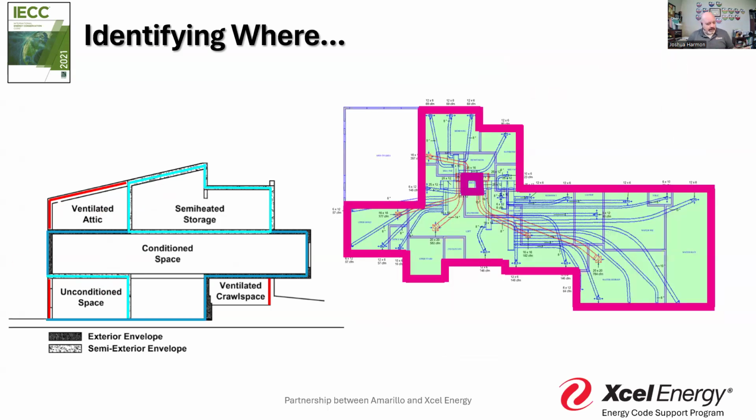And again, one of the things that was brought up here recently is this concept of rooms that contain fuel burning appliances. And it's not the appliance itself, right? It is the combustion air, the uncontrolled access to combustion air that's going to cause the problem, and why we need to think about how and where we locate equipment and where we locate ductwork.